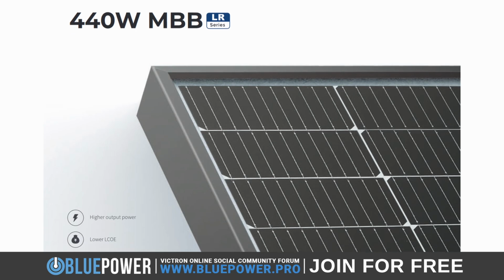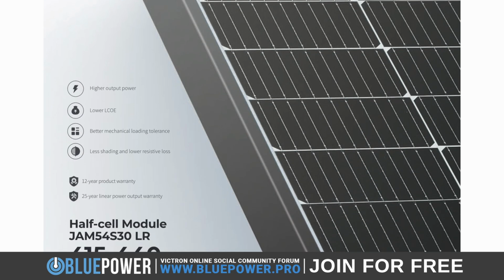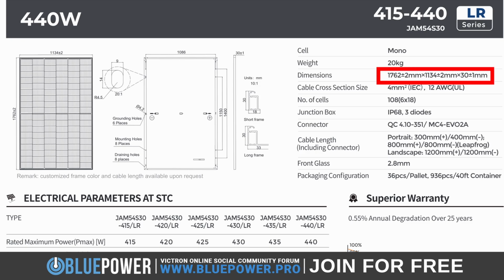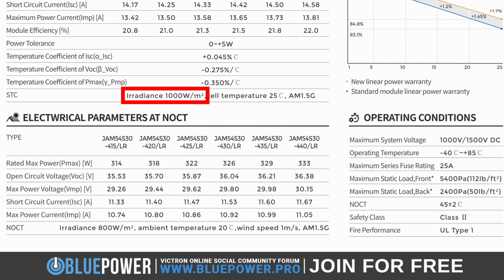Great. Let's now enter some values from a JA Solar Module's spec sheet in order to better understand this. I will be using the 425 watt model, highlighted here in red, for this example. Here we can see that it has the following specs under STC. A VOC, or open circuit voltage, of 37.91 volts, an ISC, or short circuit current, of 14.33 amps, VMPP, or maximum power point voltage, of 31.3 volts, an IMPP, or maximum power point current, of 13.58 amps, a physical length of 1762 millimeters and width of 1134 millimeters, and lastly, an irradiance of 1,000 watts per square meter.